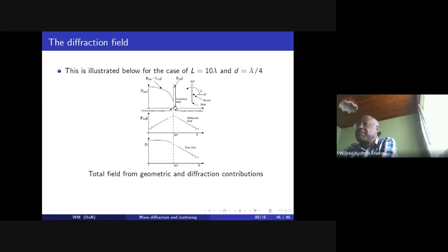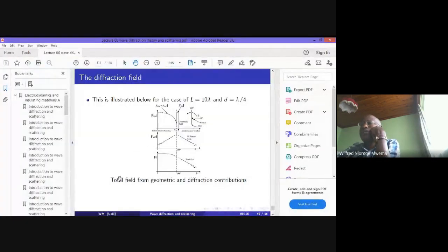So when you are working with PCBs, you've been told that whenever you are exposing your circuit onto the PCB surface, you are supposed to make sure that the printed side of your transparent paper is lying on the PCB itself, so that any diffraction that would appear because of the light passing through the thickness of your paper does not blur the edges of your circuit, and therefore you'll get the dimensions correctly. This is something you have to always remember, that diffraction is a real phenomenon. So that's what we have to say for diffraction.